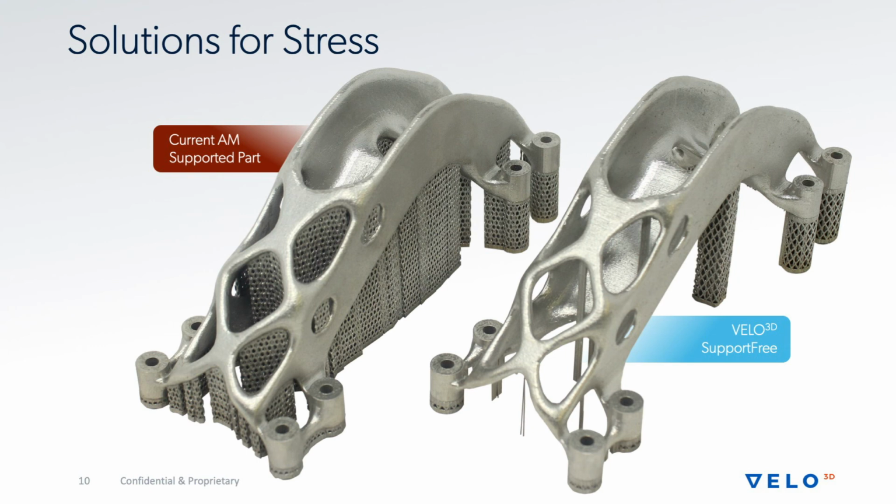if you're printing at a specific angle, that it's optimized for that angle, and so that you don't have surface breakdowns and warp. The goal here is to control the thermal behavior and control the thermal gradients of the part so that you don't lead to these defects. The example I'm showing here is a fairly complicated design. It's a topologically optimized bracket.